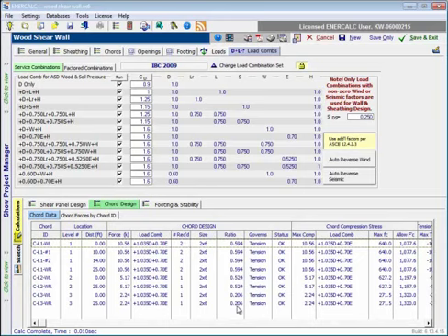The ratio is indicated, so 20.6% utilization of that single 2x6 at level 3, moving to something more like about 60% utilization of the double 2x6 in the bottommost story.